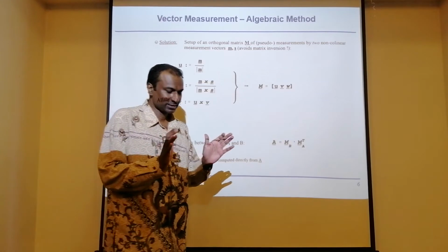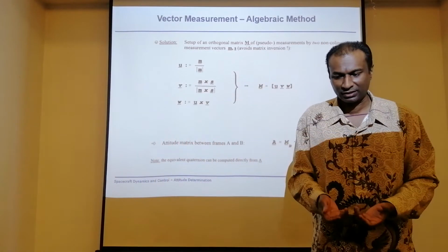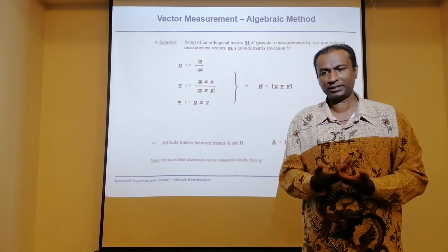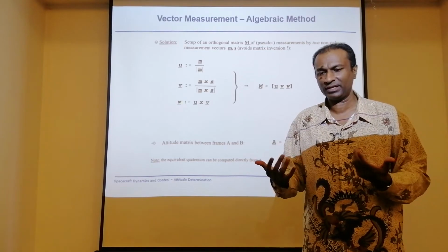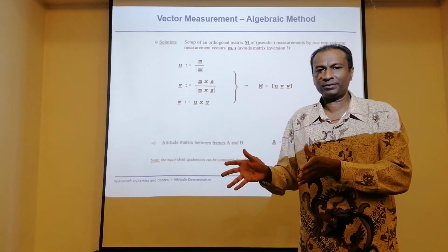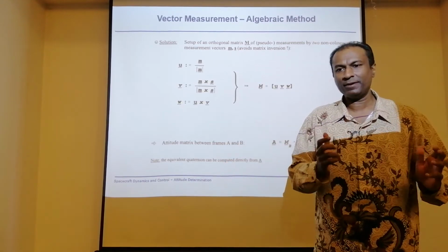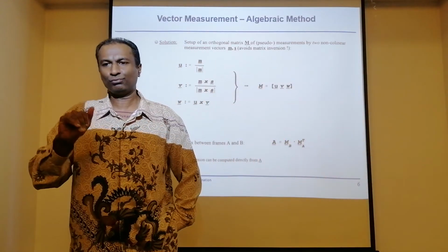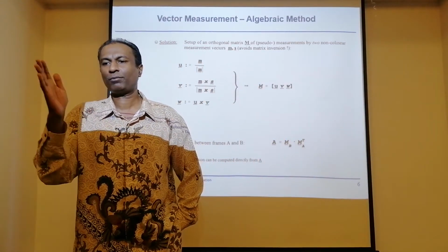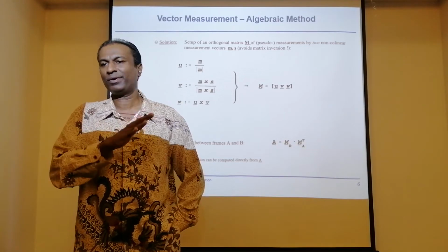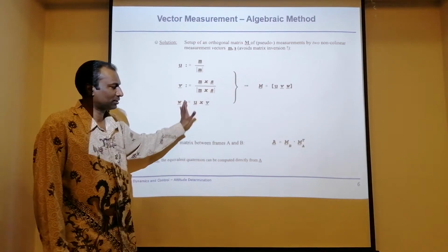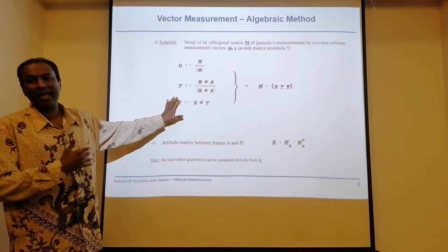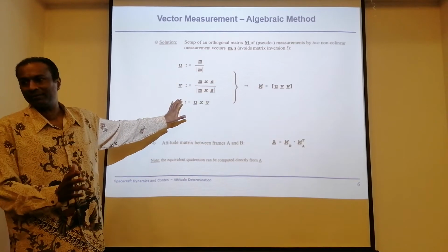So it is like this. When you have a measurement, you just have to take this measurement and look at it. You have X, Y, Z. You have the actual alpha, let's say alpha 1, alpha 2, alpha 3. Take that and rotate it into frame A or B. Now, in the exercise that we have done before, all these were given to you, and we just asked you to rotate from one frame to another frame, and vice versa. So this is the fundamental. This is what exactly is happening, and that is the reason you end up rotating.